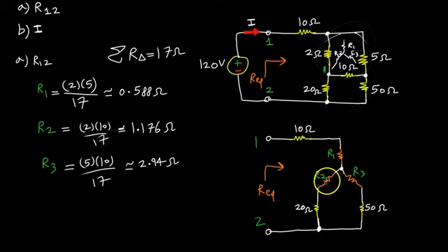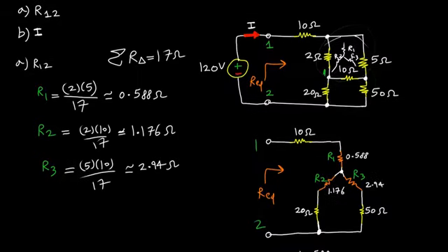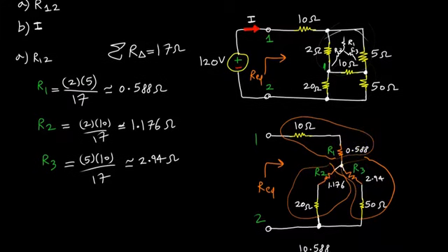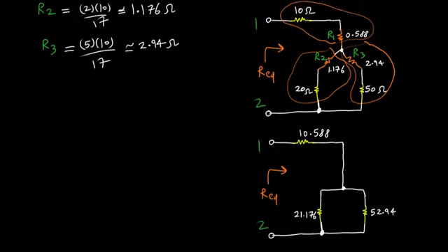now that we found some values here, we can go ahead and simplify the circuit down even more. In this case, I've written the values that we just found near the resistor labels. The next step is to combine these resistors in series, and these resistors in series as well, and also these resistors. Because we've had some practice, I'm going to skip some steps and do these simultaneously, so that I get 3 equivalent resistors of the values shown here.